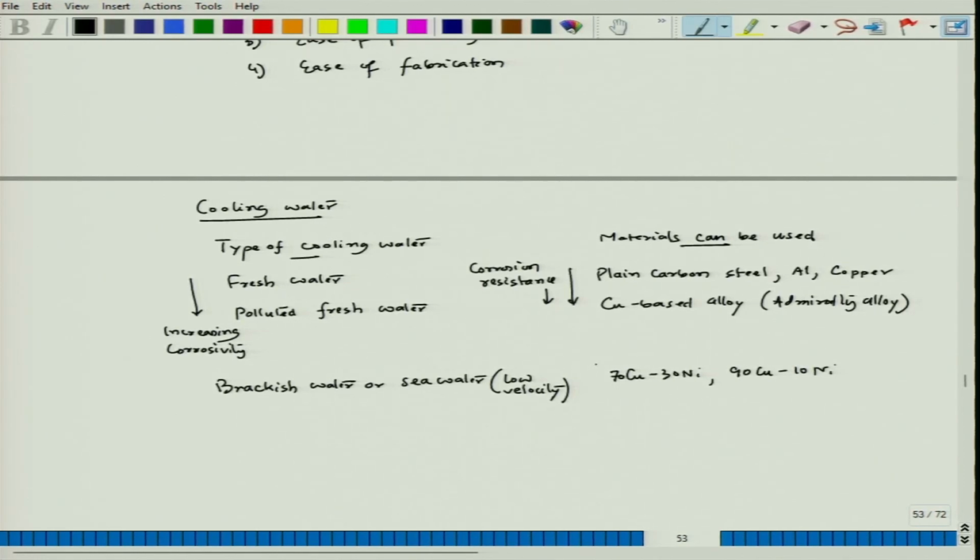So, these alloys can withstand the corrosion ability of those medium, and in fact, you could see that the corrosion resistance is further improving in this particular direction, downward direction, as well as the corrosivity is further increasing as we go down. So, that means if we fix a particular acceptable limit for attack, then we can actually decide which are falling on the right side of that acceptable limit or left side of that acceptable limit.